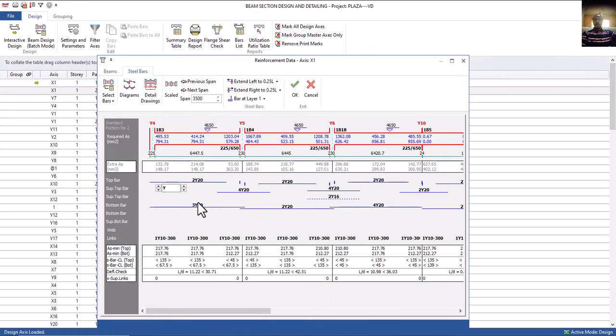Okay, so at this point I want us to listen very well and be careful. If you look at this now, you'll notice our reinforcement is scattered, isn't it? They are somehow scattered. You can see at the support, we also have at the support, at the span, and all of that. Which is not okay. Practically, this is not how we arrange our reinforcement.